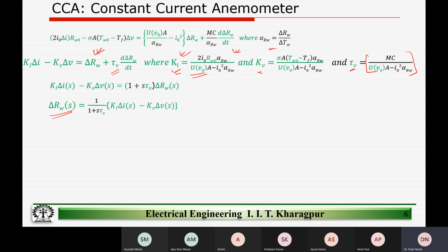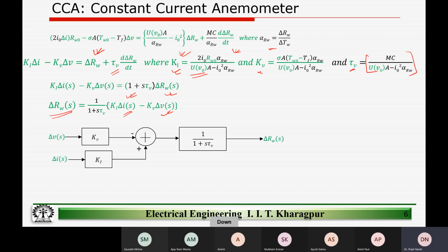As electronics or electrical engineers, it is easy to measure the values of resistances or capacitances, right? So what we are doing is we are trying to come up with a transfer function, how the resistor is going to change with two input variables. One of them is, of course, the current, and the other is the velocity of the fluid, right? How does it look like?